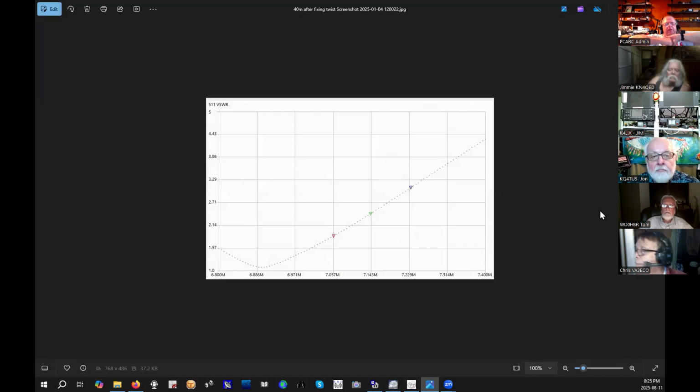Chris, I believe a few years ago, you used it to test out a duplexer design. That's a different story. For things like that, the S21 function is good because those graphs come up live on your screen. You can continuously do them. And as you're adjusting a variable capacitor on a duplexer, or let's say you're spreading apart the little coils, you can actually see the humps of your pass bands and your blocking bands come through live. It's really quite a tool.